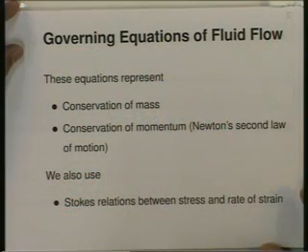Let us begin our study with the governing equations of fluid flow. In conduction, the major governing equation was the equation of conservation of mass. There was no flow, hence the equation of conservation of mass and equation of conservation of momentum was more or less trivially satisfied, and we had to study conduction essentially using the equation of conservation of energy. Whereas for fluid flow, the governing equations represent entities related to flow.